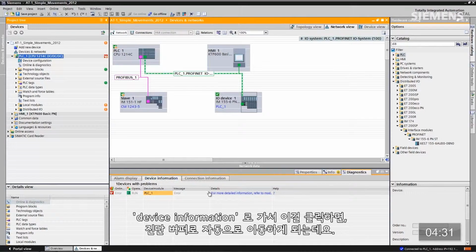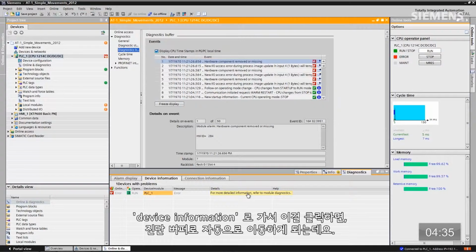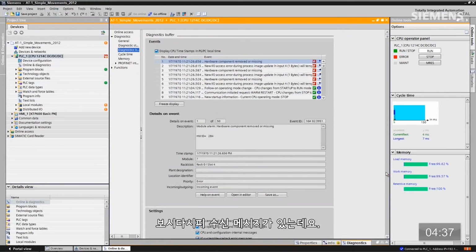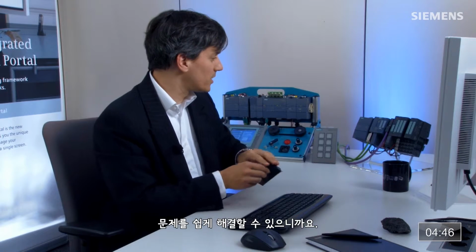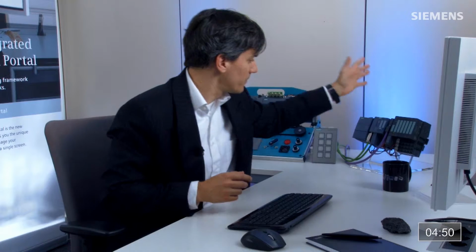If I come down to the device information and click on this right here, it'll automatically take us to the diagnostic buffer. And as you can see, it is an incoming message. It is an error for rack 0 slot 4, and it says this hardware component is removed from that particular rack. That is correct, so I can solve the problem easily. Let me put this back in the rack real quick.